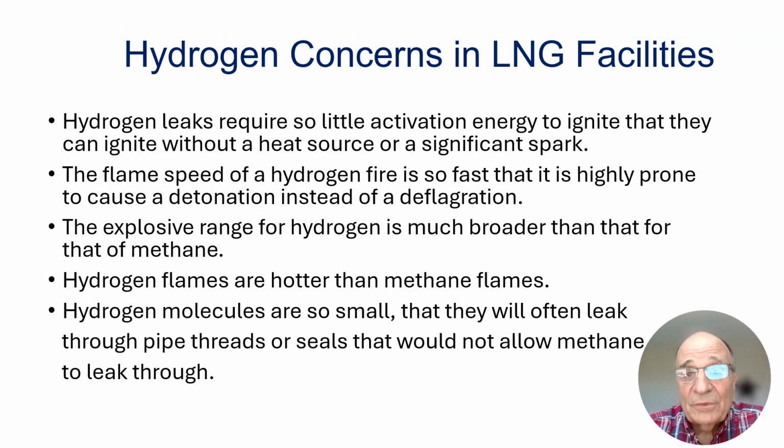Hydrogen is not something that we've had a concern about in the past in LNG facilities, but it might be in the future. So let's just touch upon some of the concerns. Hydrogen leaks require very little activation energy to ignite. In fact, if the hydrogen is concentrated enough, it can almost auto-ignite. The flame speed of hydrogen in a fire is so fast that it is prone to detonate instead of deflagrate.